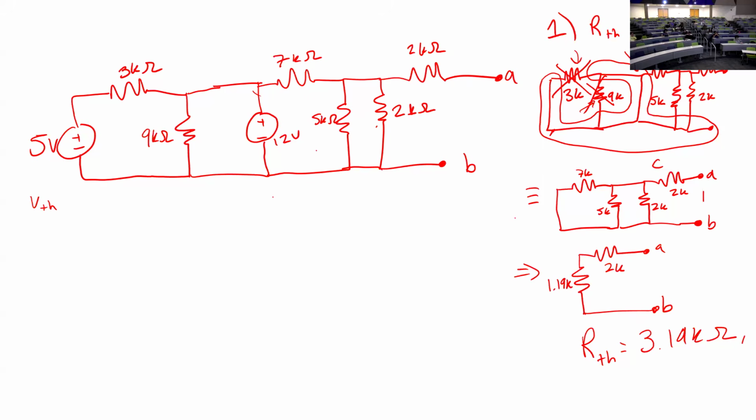Yeah, right. So if we have an open on both ends, how much current is flowing out of both of them? 0, right? I have a dead end. No electrons want to go that way. So if I have 0 amps going this way, then how much voltage drop do I have across this resistor? Across this one here. How many volts am I losing if using Ohm's law, V equals IR, I is 0?